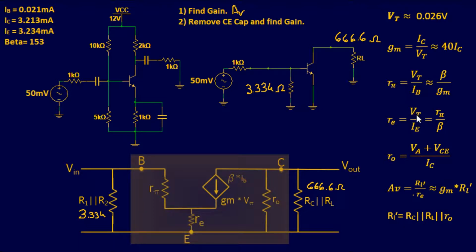So now our thermal voltage is 0.026. Now in the slides, we did a big calculation and it was 0.025 and some change, and you round up to 26. This was taken at 300 degrees Kelvin. That's very average room temperature. Some of your books may have 0.025, some of my books had 0.026. Whichever one you use, you're going to get a very similar answer. So be advised, either one of those will work, hence the "it's close enough" sign.